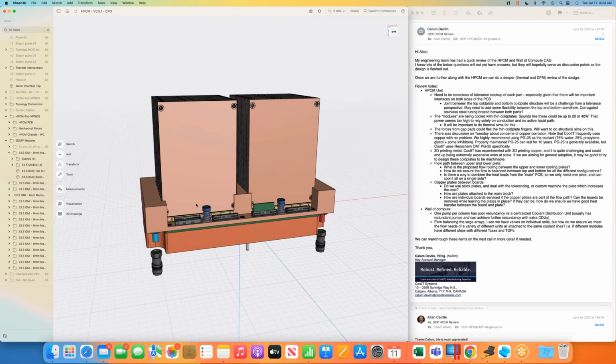So what we're doing is saying, let's make the water management the first primary thing to manage, and make the electrical the cabling piece. At the moment we've got water cabling and we've got electrical through PCBs. And if you notice with PCIe Gen 5, you're starting to see a lot of cables because the signal integrity of the PCBs isn't good. So we're already migrating to cables, even at Gen 5, let alone Gen 6 and 7. And if we're going to go towards cables, and then towards optics with silicon photonics, in a world of cabling on the electrical and signal side, it makes sense.